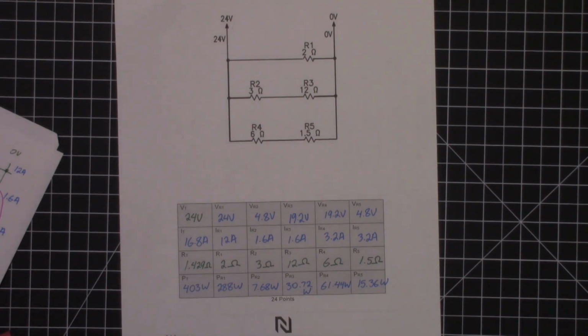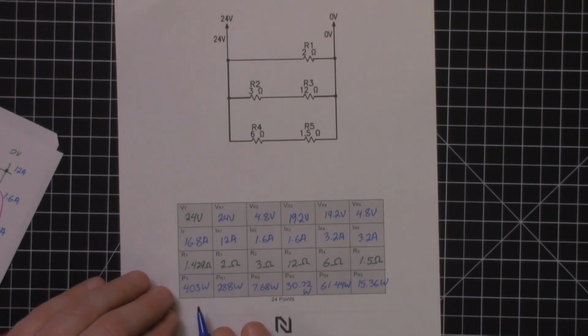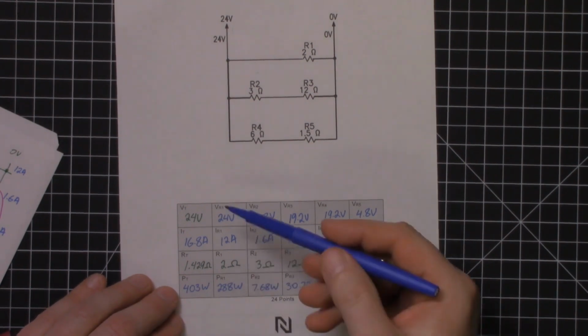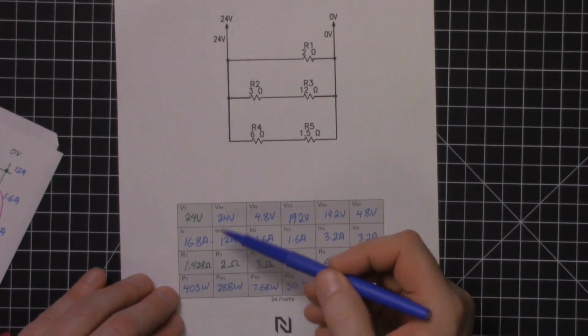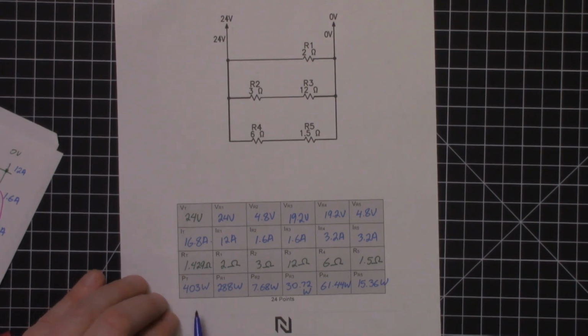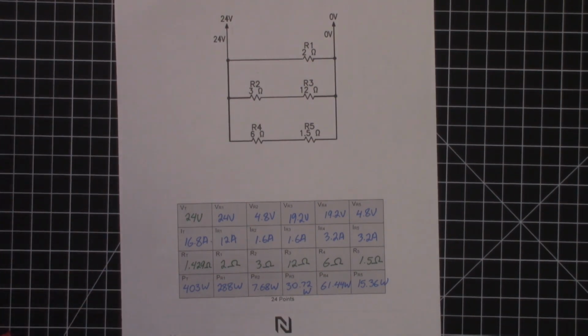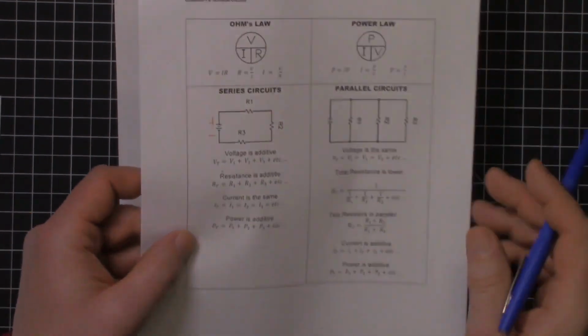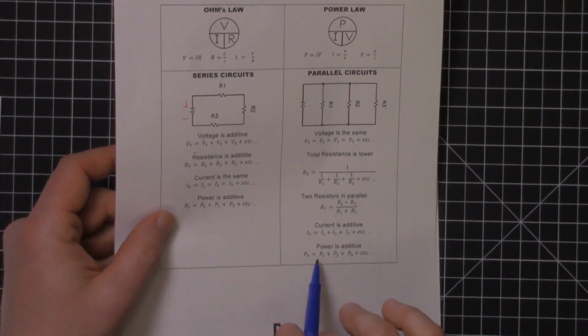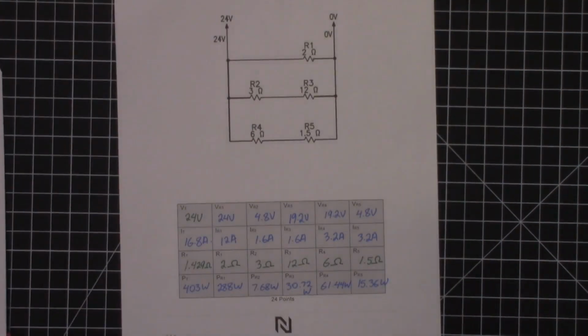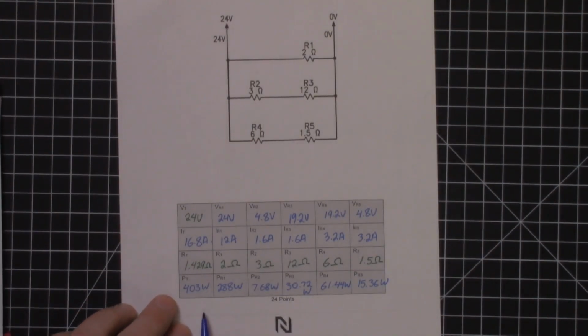All right, so I paused the video for a second there and did the routine business of calculating the powers for each of them. Again, voltage times current for each. And the interesting thing here is, regardless of what kind of circuit it is, series, parallel, what have you, powers are always going to be additive. It's the case for both series and parallel circuits. So if we want to double check our work after going through one of these circuits, the total power is equal to the sum of all of these, it should be this 403. And that's a great way to check your work on any of these circuits.